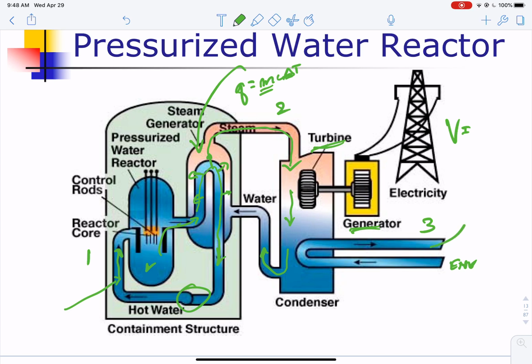And then this water can go to a number of places. For example, it can go to a cooling tower where evaporation cools it down, and then the remaining water that doesn't evaporate can be returned to the environment or recycled. It might go to a holding pond. In any case, it's got to be returned to the environment barely above the same temperature that it came in.